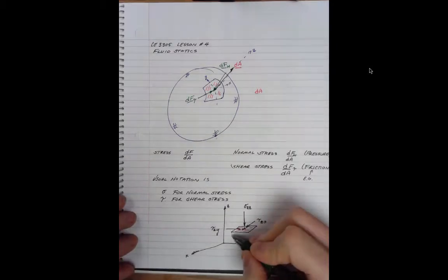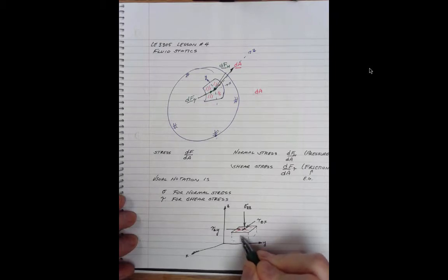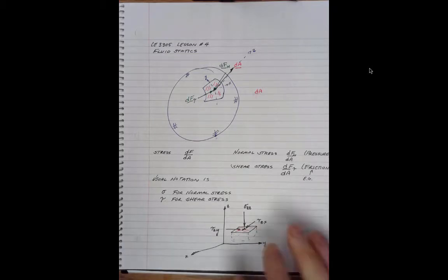Then if this object became a cube, for instance, there'd be 3 times 1, 2, front face, back face, that's 3 times 2, and 4 is 6, it'd be 18 stress elements. Okay, so the normal stress by convention is into the plane, and the first subscript is the direction of the normal vector to the plane. The second subscript is the direction of the stress application.